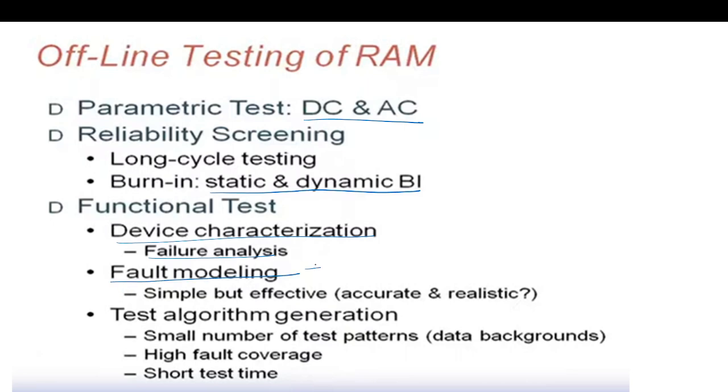Fault modeling means, say we have a particular defect. This defect is modeled using the fault models. And they're simple but effective, accurate, and realistic. Test algorithm generation: a small number of test patterns, data background, which should give high fault coverage and short test time.